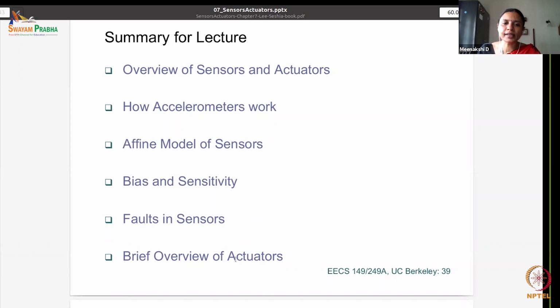So there could be various kinds of interrupts. There could be triggers, there could be responses. The trigger could be a level change on an interrupt request pin or writing an interrupt pin configured as an output. Responses could be to disable interrupt, to push the program counter onto the stack, several different things. ISRs have to be designed very carefully, in such a way that they don't end up eating into the main functionality. But the problem with ISRs is that they make computing very non-deterministic. So you have to be careful.